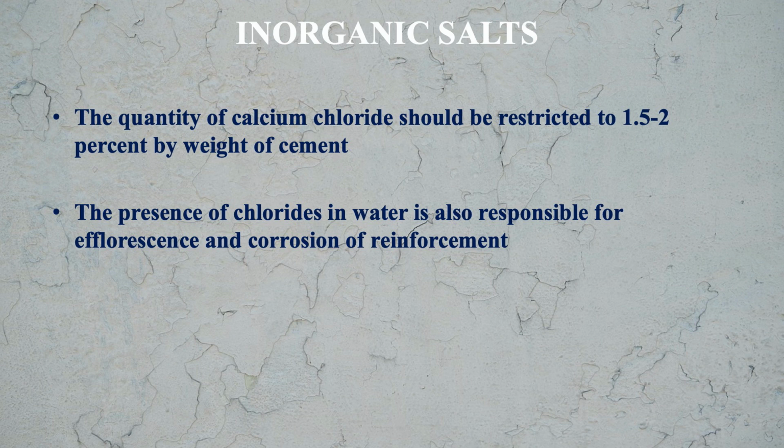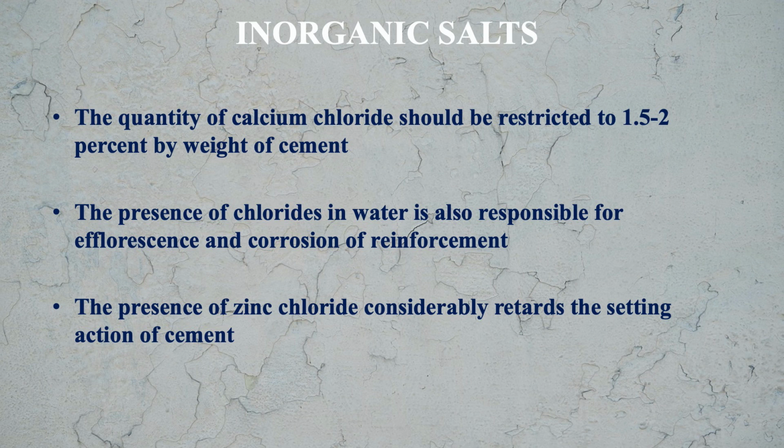The presence of chlorides in water is also responsible for efflorescence and corrosion of reinforcement. Means reinforcement will also be affected because of presence of chlorides in water. The presence of zinc chloride. What is the effect of this zinc chloride? The presence of zinc chloride considerably retards the setting action of cement.